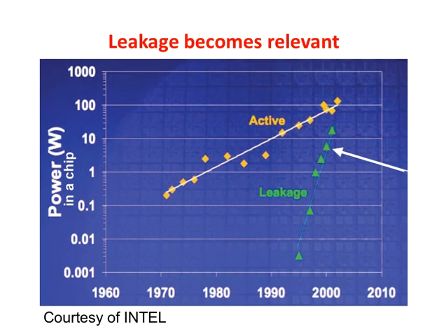So as I mentioned before, in the 80s, you could discard the leakage. Then at some point, it started to matter a lot, because you are decreasing the threshold voltages, and therefore you are increasing a lot the static power consumption. And you can see that it's becoming important here. In 2001, 2002, the two become comparable. And if you do not change the type of scaling, the leakage power consumption becomes absolutely dominant, and it ruins everything.